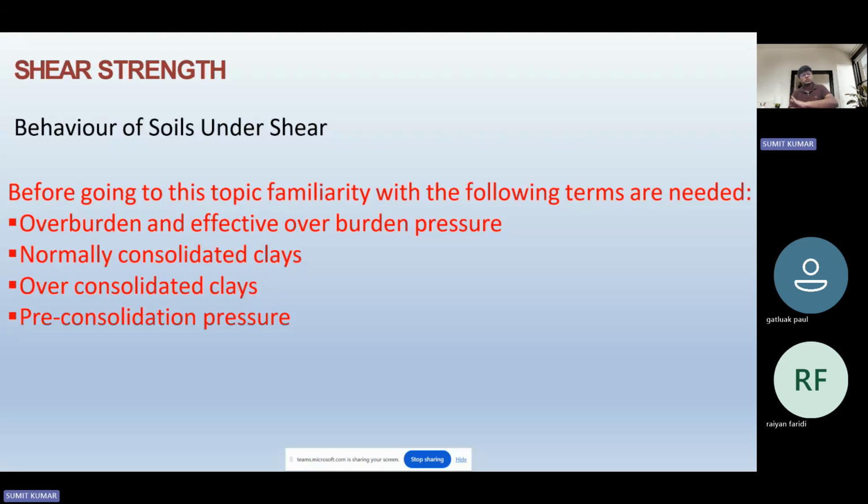Now those structures are demolished, so the stress at that specific location gets reduced. But in the past, as the stress was applied over there and soil is not an elastic material that can regain its shape, it is already under very much stress, so the consolidation settlement may be less. That point is significant while stating this. Now the next one is the pre-consolidated pressure. Pre-consolidated pressure is a term which we discuss elaborately when we move to the chapter on consolidation.